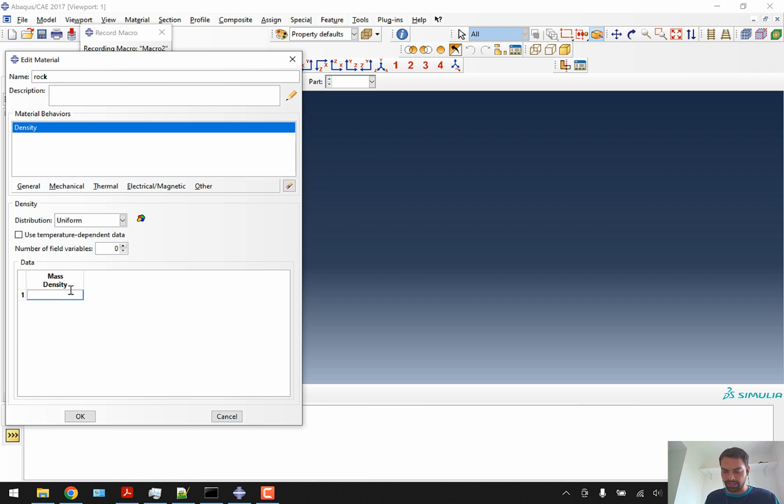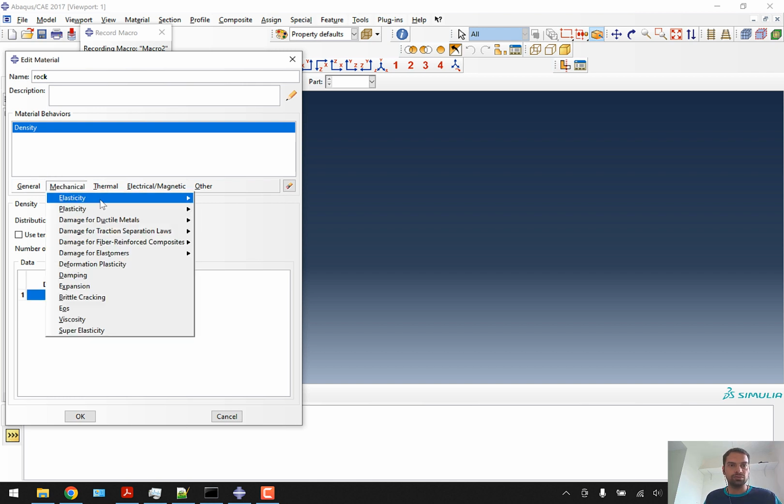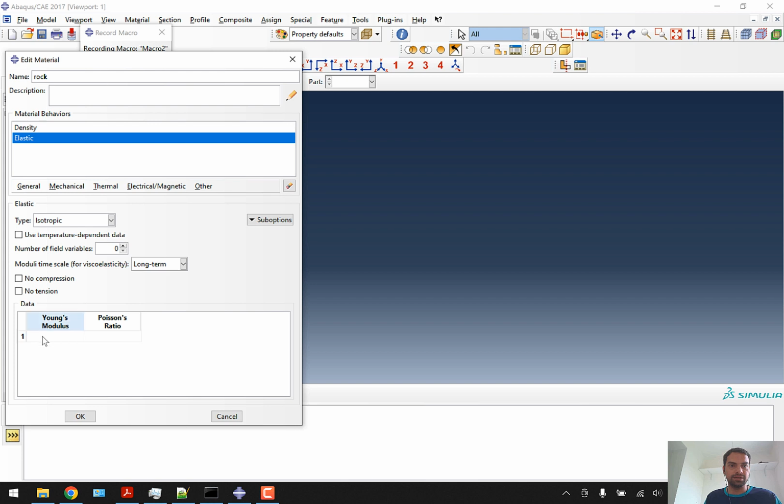So I have the density of rock as 2400 kilogram per meter cube, so you should have the units very much same, kilogram, meter and newton, and like that. So the Young's modulus I have is 100 megapascal, so E6. Poisson ratio is 0.35. Then I have the C and phi parameters.